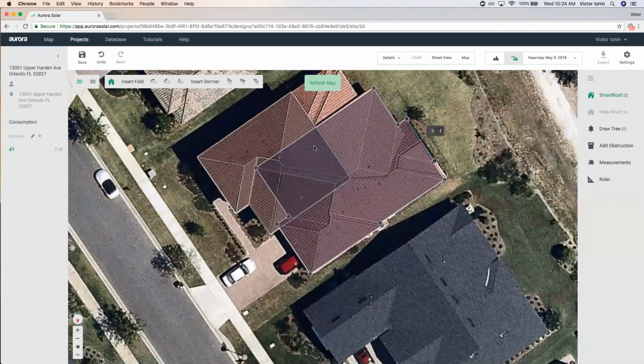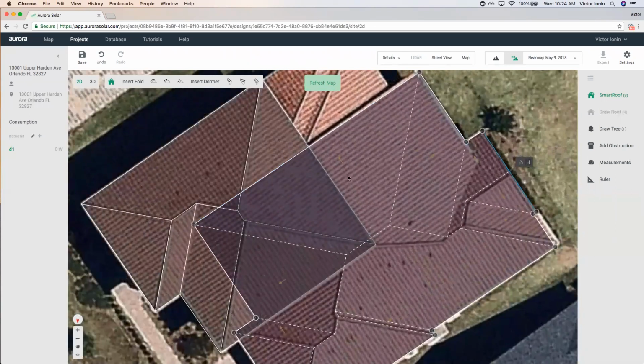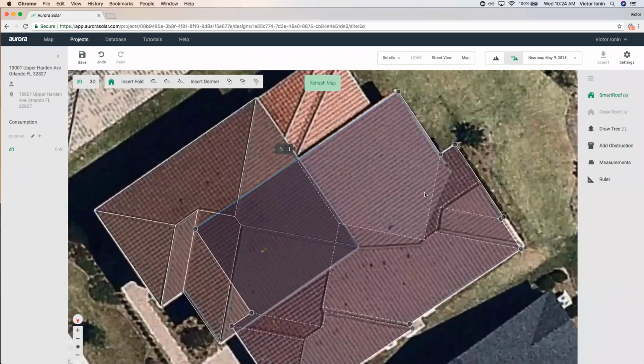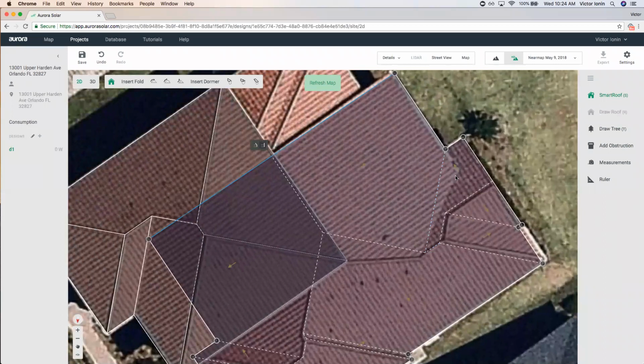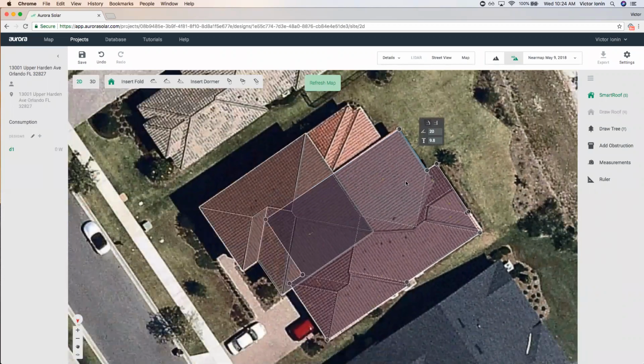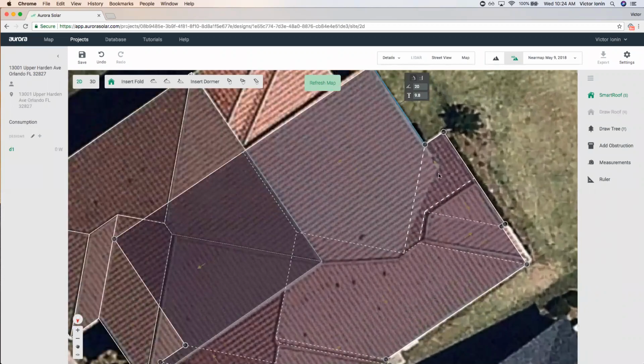Everything looks pretty good. Oh, the back of the home, it's pointing northeast. I don't need this big chunk of roof pointing northwest. So let's unpitch that. So that's great. So everything lines up except for here. Now, it's weird. The valleys don't really line up with the other valleys. And one of the things that is happening is that this section pointing to the northeast is probably at a different tilt. It's probably at a lower tilt, just judging by the angle of the valleys. Now, as you design more and more, it kind of becomes intuitive.